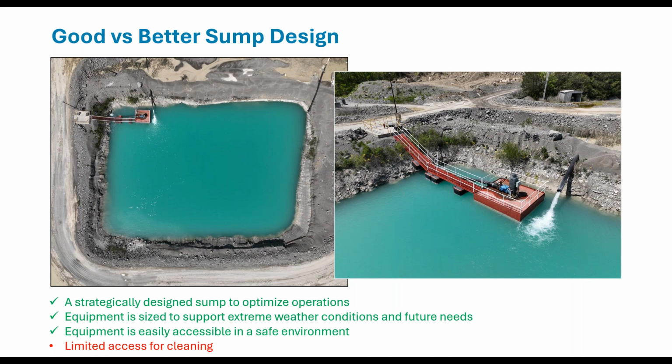I spoke earlier about water storage as a design consideration. This sump is properly sized to make good use of the water that is being removed from the mining pit by using it to feed the main processes of the plant. It also has extra capacity to handle additional inflow from potential weather events, heavy rainfall.